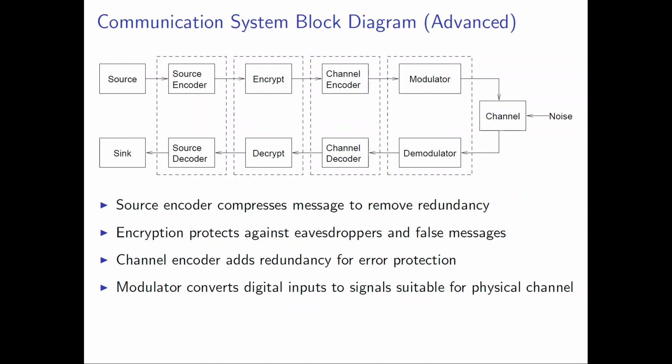In the previous lecture when we gave the example of 100 megahertz and 900 megahertz, we asked which signal can go farther, 100 or 900 megahertz? 100 can go farther. The coverage of 100 is more than the coverage of 900 megahertz. But why do we use 900 in our phones? We don't use 100. Because of the antenna. Yes, the antenna is lambda over 4.